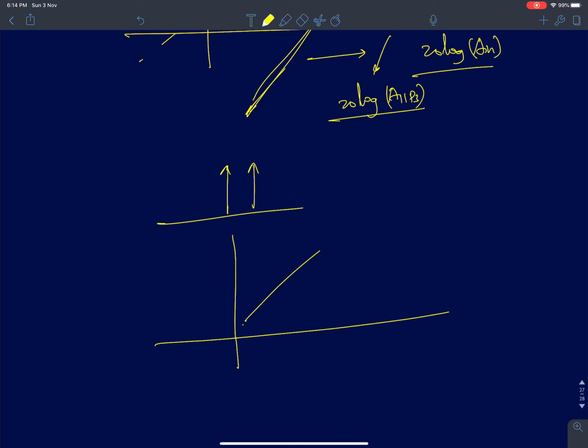We'll plot this graph of the first harmonic. We'll just measure the first harmonic, that is the harmonic strength of these two. We'll feed 2 equal amplitude signals and plot the graph. Now understand that as you keep increasing the amplitude, the gain starts reducing. There will be gain saturation, right? We discussed this in the previous lectures. Similarly, we'll also monitor the third harmonic term. The third harmonic term is going to rise faster, but that is also going to saturate. Eventually nothing will go to infinity, because the amplifier is going to saturate.